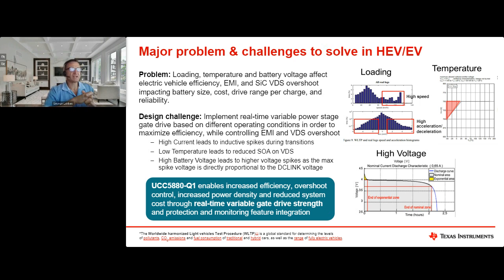And then when you look at temperature, conceivably, you could start a vehicle at very cold temperatures. And cold temperature does affect the safe operating area of the switch. It actually lowers the working voltage. And in this particular case, you see a decrease of 50 volts on the working voltage of the switch.